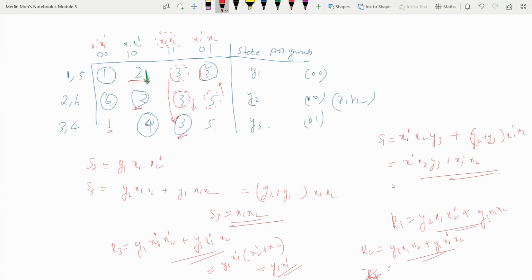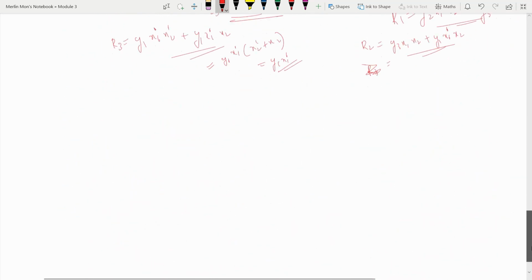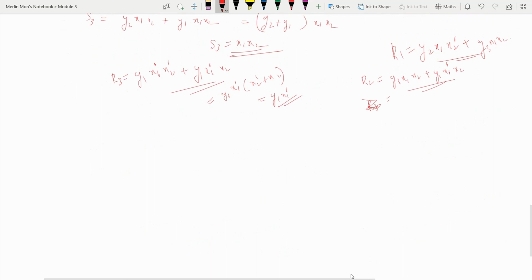So before that, how are you going to represent a flip-flop in a ladder diagram? We will see that. So a flip-flop can be represented like this in a ladder diagram. Generally, these are the two rails. We will connect a push switch here, and this will be the set input, and we will connect a normally closed push switch also here. This is normally open, and this one is normally closed, and this will be our reset button.